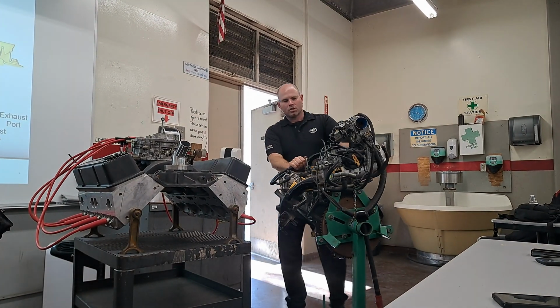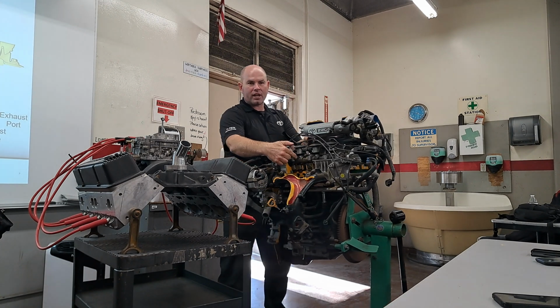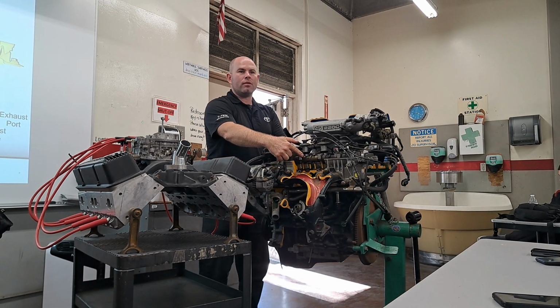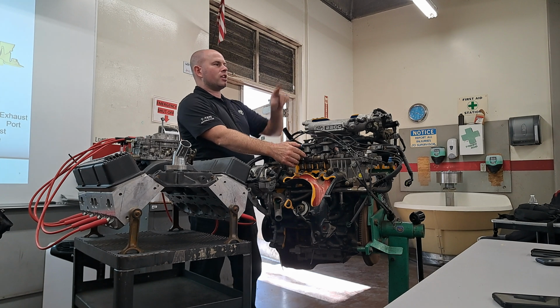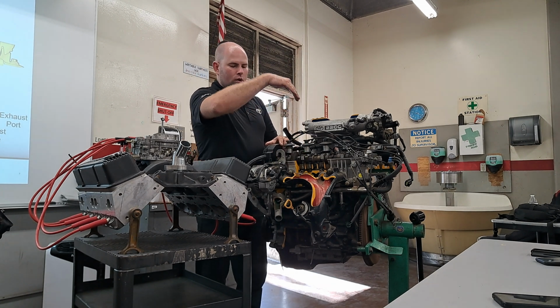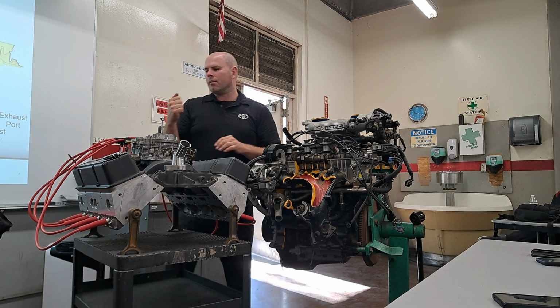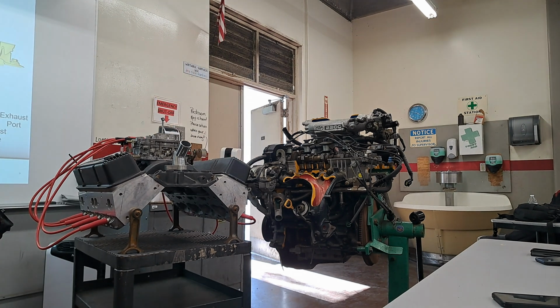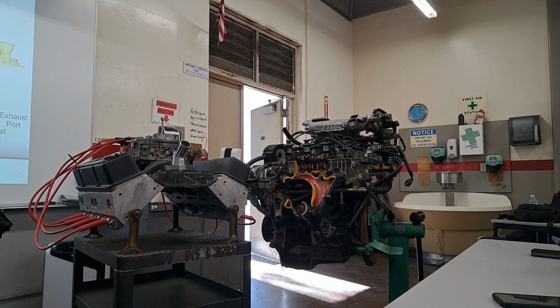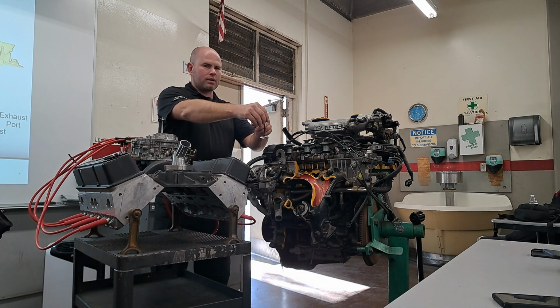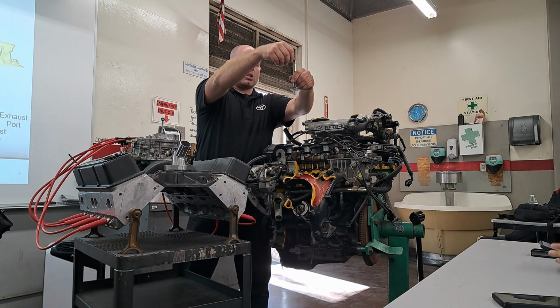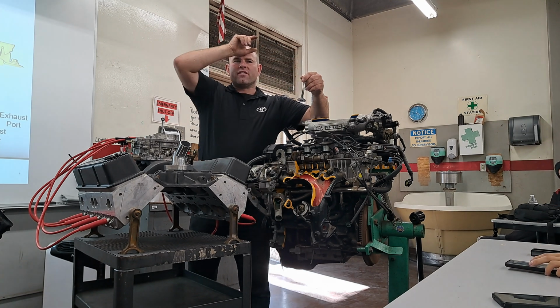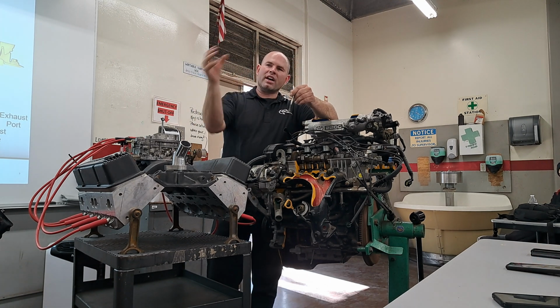So we've got a camshaft right here. You can actually see the lobe sticking out. As that camshaft turns, it's going to go around and basically push on the valve. So I brought a valve over here. I'm pretty sure that I had a cam, but I guess I forgot. If you look, as that cam comes around, it has the ability to push this valve down. When the valve is down, if it's the intake valve, that's when the air flows.